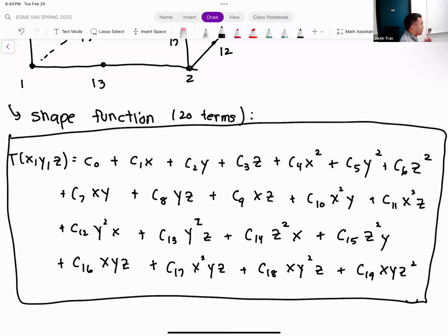That's why, generally speaking, if you can get a quadratic hexahedron mesh, then you're good on any solution accuracy problems, and you could probably get away with a fairly coarse mesh as well. All the benefits of a quadratic hexahedron are the same as before, so I'm not going to repeat: a better solution dependency, better solution quality, at the cost of computing all this extra.